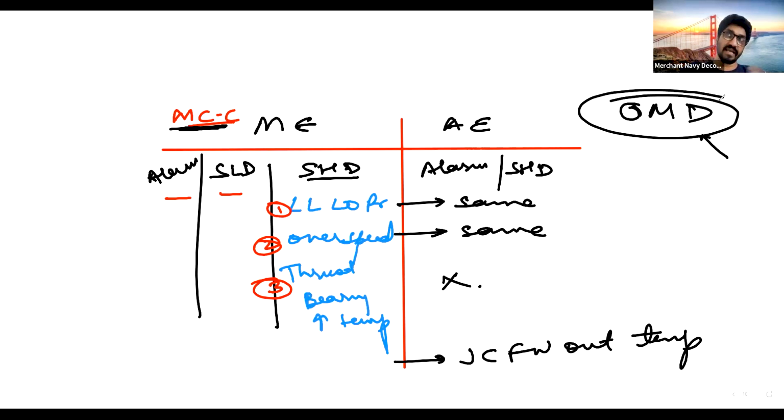Same like rain. Before becoming rain, it was water vapor because of some heating effect. In the same way, because of heating, oil will become vapor, and because of cooling, this vapor will become mist. This mist is explosive.